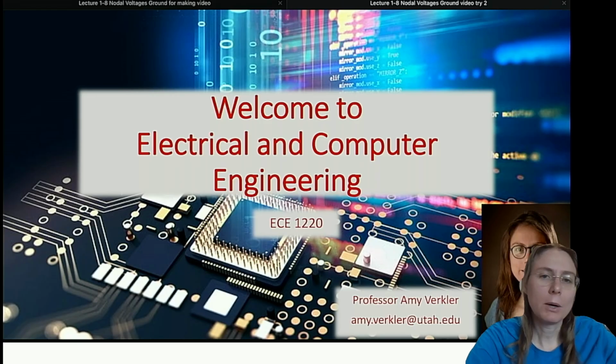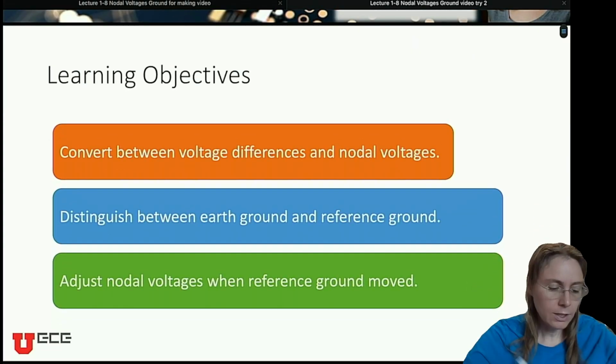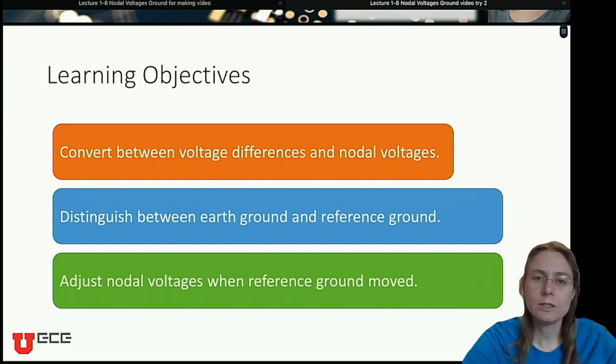Today we will be talking about nodal voltages and ground. We are going to learn how to convert between voltage differences and nodal voltages. We're going to learn about earth ground and reference ground, and we're going to learn how to adjust nodal voltages when reference ground is moved.